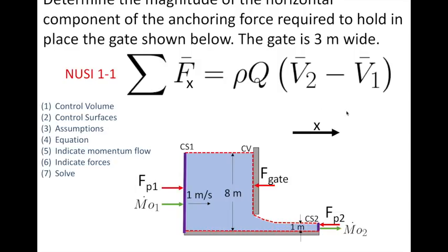I've put this big X arrow on here to indicate that I'm only solving everything again in the horizontal, which is my X coordinate. And in this situation, I am entirely sure that the force must be acting towards the left. So this time I have made that assumption and drawn my arrow towards the left. And I want us to think about how that influences our final result when we get to it. Sometimes, though, it is not obvious in which direction the force might be acting. Sometimes it's just a little bit too complex. Sometimes you don't even know because it depends on the flow conditions.